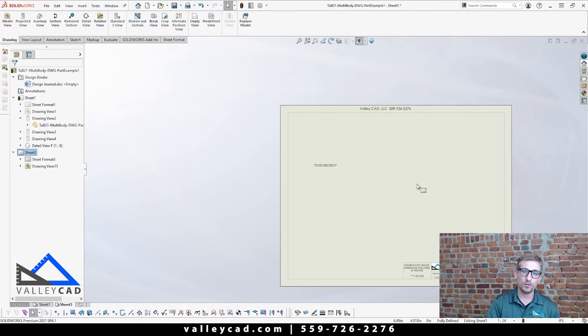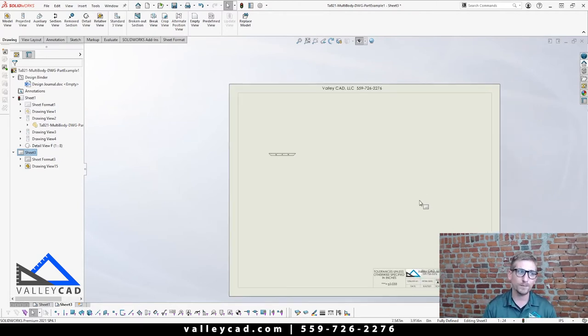So the other thing that we're gonna do, being on SOLIDWORKS 2021, if you notice right below me, yes, there's a little traffic light there, but right next to it, it says 1 to 24. This is actually my sheet scale currently. What's really cool is I could click on this. I know my head's blocking it, but there's a flyout that comes up, and it has a series of different scale factors that you could choose from. So in this scenario, I'm gonna come up to that 1 to 8 scale and make it so that my entire sheet is set up that way. So that way, this drawing view is gonna be set to 1 to 8.